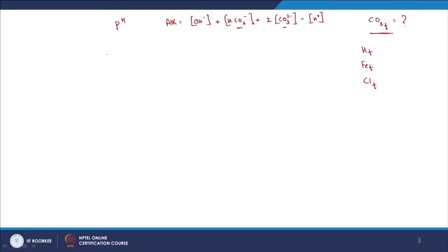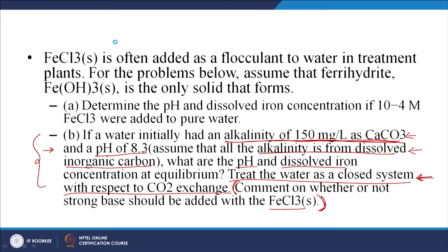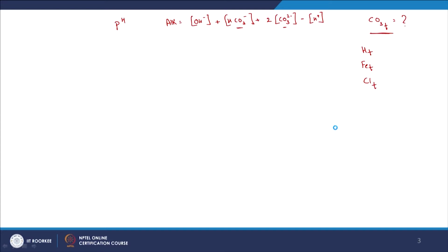So alkalinity, again, I know this particular value that was given. I think I can change the units to moles, molar units or equivalent units if required. I think it is 50 grams per equivalent for CaCO3, and I can divide and get it in equivalents per liter. Anyway, alkalinity is a known value, and how can I express this equation?